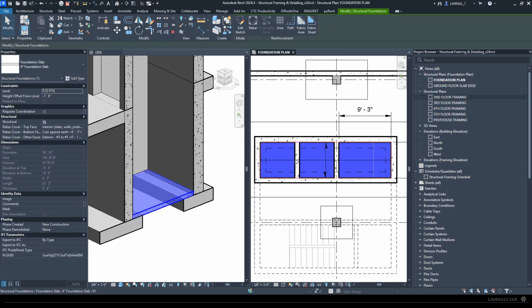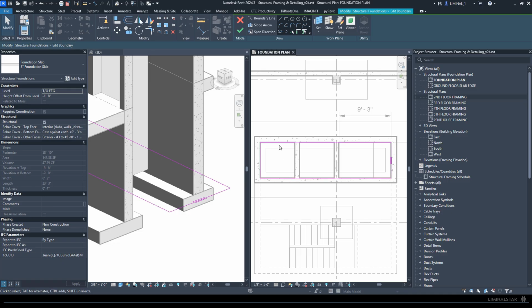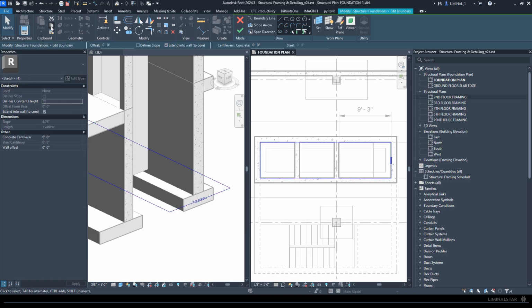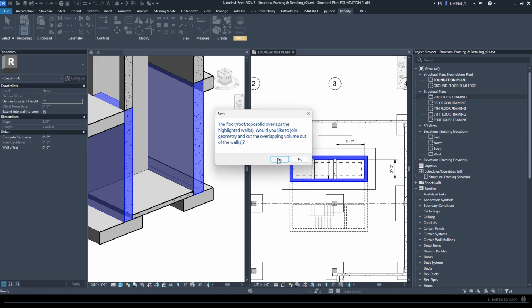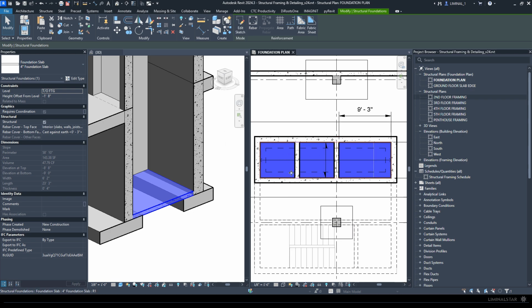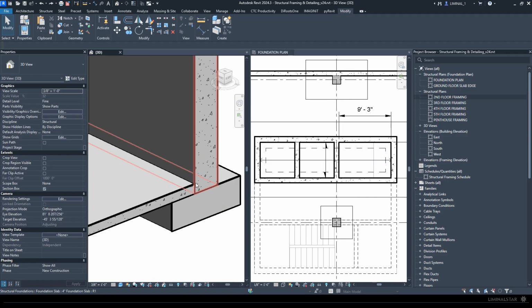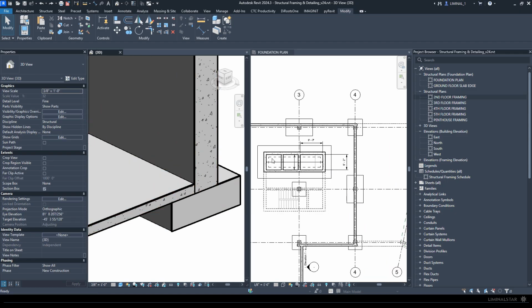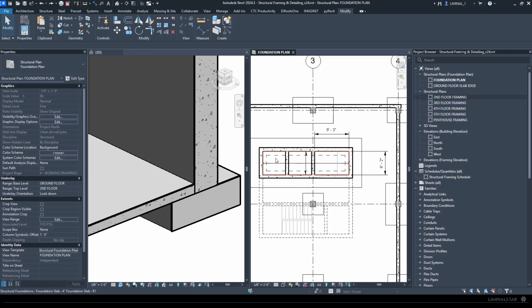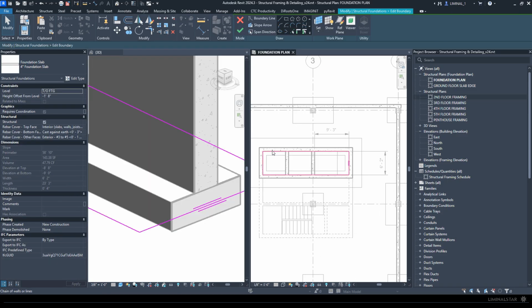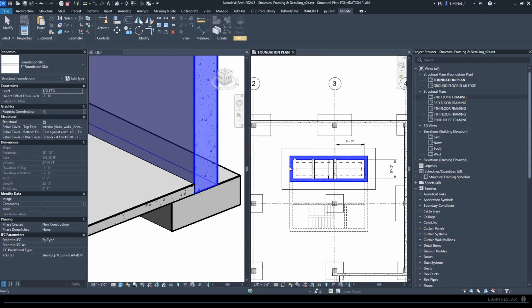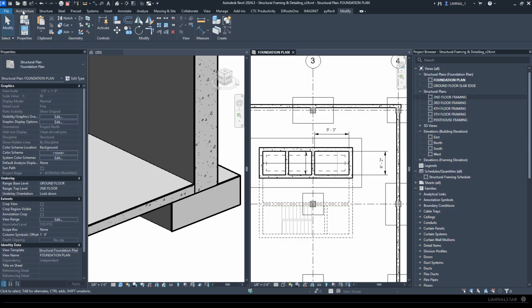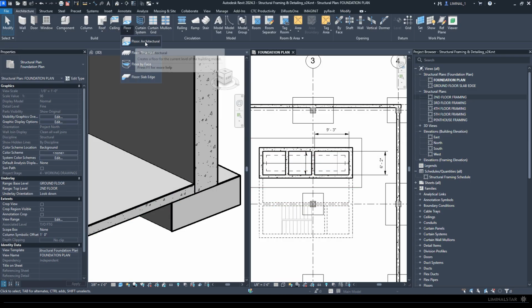And then selecting my slab, I'll hit Edit Sketch and just select that sketch and copy that to my clipboard. Okay, it says, do you want to remove the overlapping geometry? I'll say yes, sure, that's fine. It's not going to, because this is going from, well, actually, it's that joint right there, right? So I should have this sketch saved. Really what I'm trying to do is just get the exact perimeter of that slab so that I can throw another slab right on top of it. But this slab is going to actually be a floor.